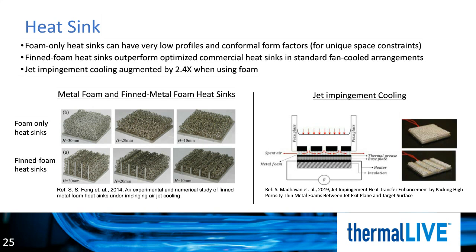Finally, let us look at some actual applications. Finned heat sinks, either natural convection or fan-cooled, are ubiquitous in everyday electronics cooling applications. Foam can be incorporated into a heat sink, either as a complete replacement of fins or as a hybrid fin-foam solution. Each approach has its own place, with the former unlocking new opportunities for extremely low-profile or even conformal heat sinks, while the latter is a great way to significantly boost performance in the conventional design space of extruded fins.